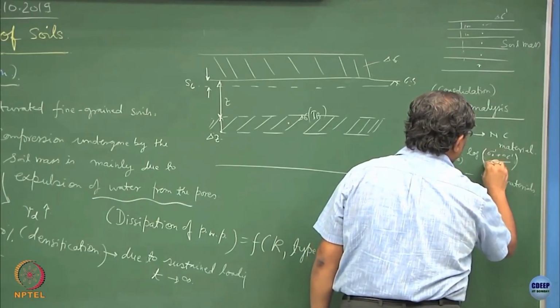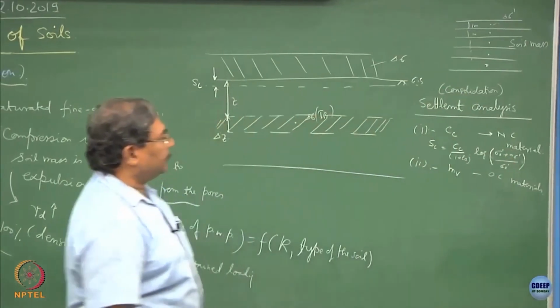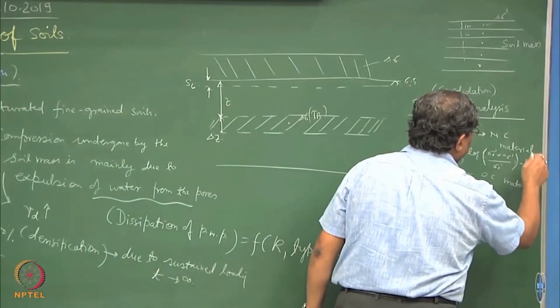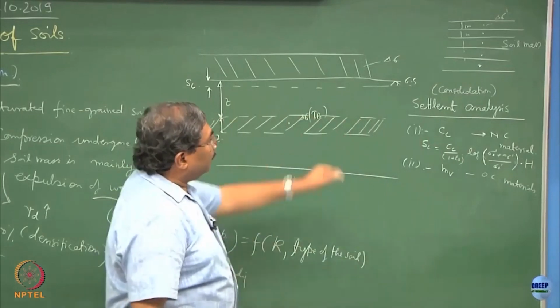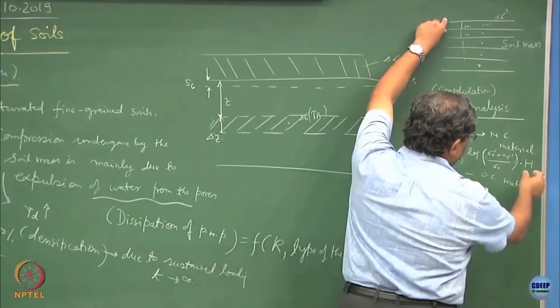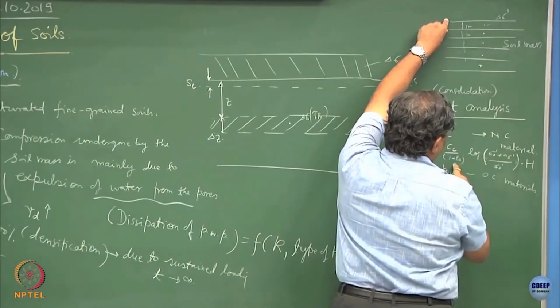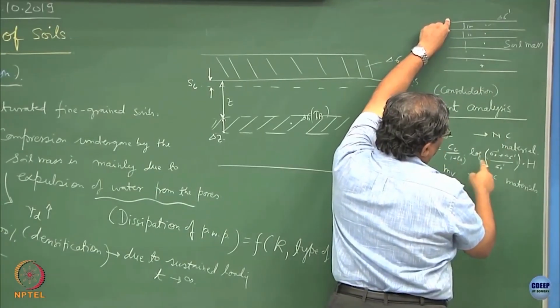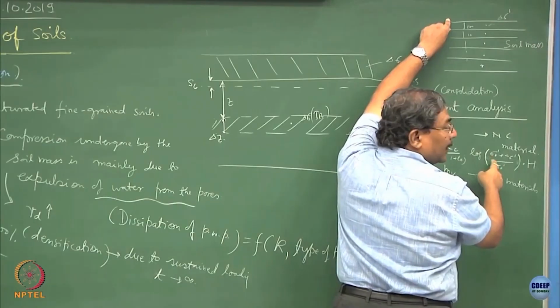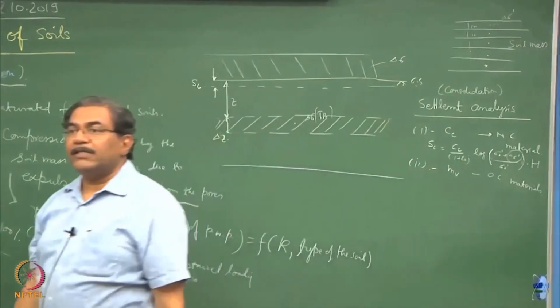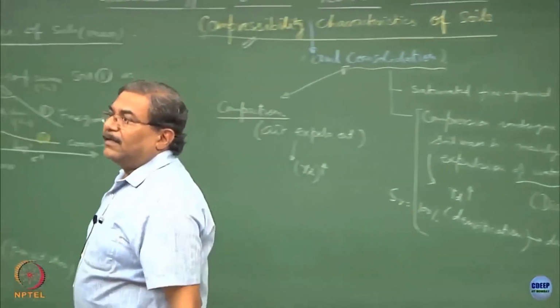Is this okay? Multiplied by the total height h. So, if we are doing it for layers, h becomes 1 meter, Cc is of each layer, void ratios are initial void ratios, you know what is the initial stress acting, delta sigma prime computation is very important, and for this you require influence factor.